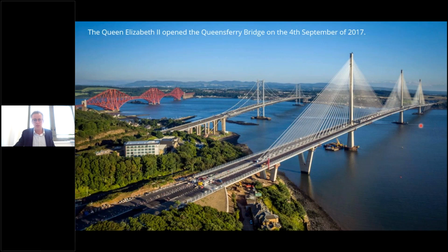So as a conclusion, the design of rigid inclusions below embankment is quite a complex problem because it involves many interactions. So between the load transfer platform and the rigid inclusions, between the rigid inclusion and the surrounding soil by friction, between the rigid inclusion and the anchorage layer. And the design of rigid inclusion also imposes to verify the structural integrity of the rigid inclusion.